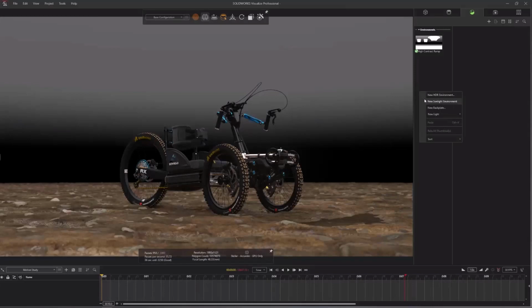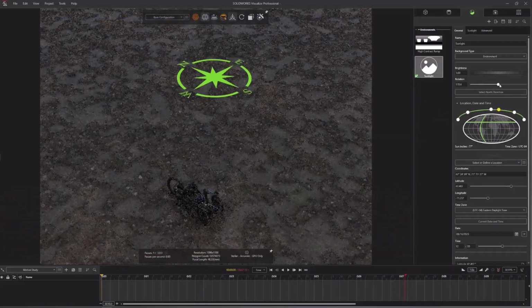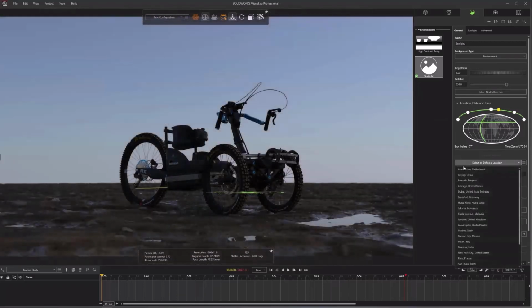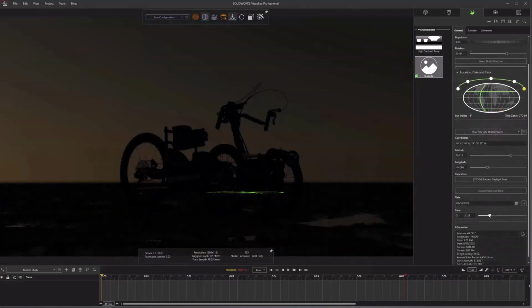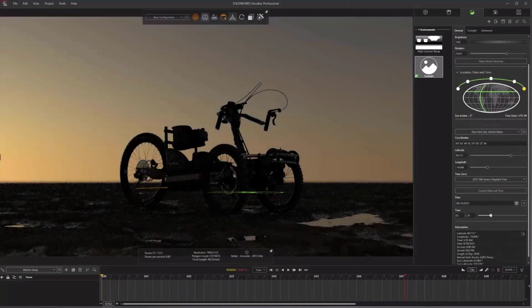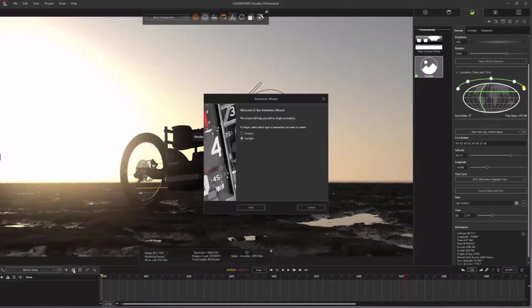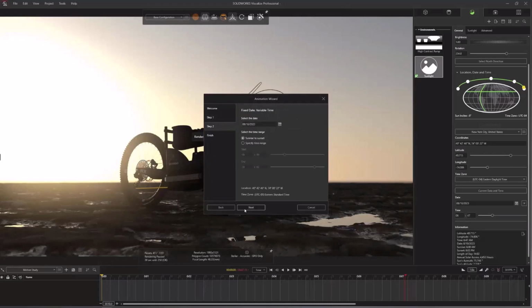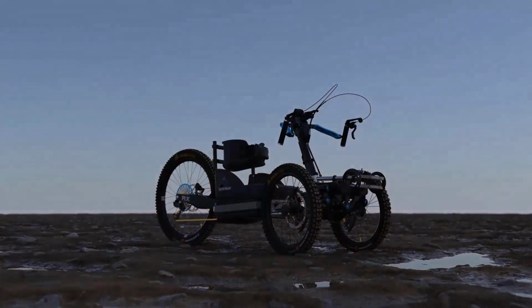Sunlight environments can now be added to see how products will look at a real time and place. The sunlight environment provides an updated compass rose so that north can be set manually or by selection on the model, a drop-down for position or coordinates can be simply pasted in, a time of day adjustment and much more. An updated animation wizard now includes controls to quickly and easily set up animations of a product throughout a day or throughout a span of time.